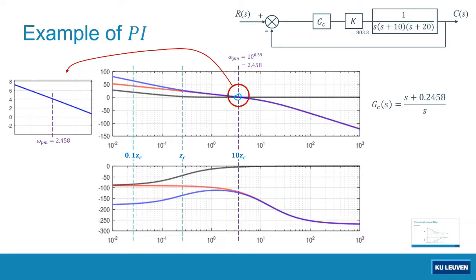In that case, to improve it further, you might want to shift the magnitude plot again about this much. Probably it will be about 4 dB. You want to shift it down about this much, and then accordingly you can add another gain to improve the PI controller that you just designed.